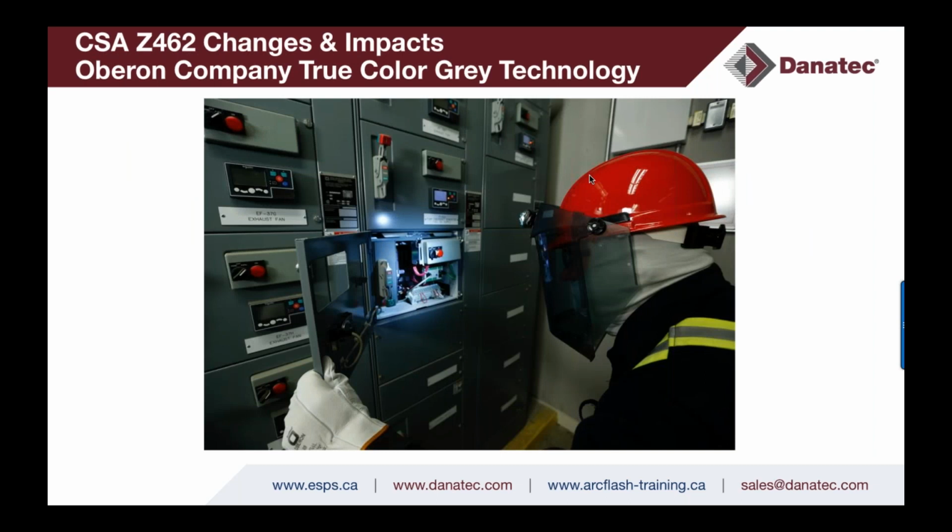So basically that's an MCC starter bucket, a qualified electrical worker, and you can see the light gray tint on the arc-rated face shield. What happens is there is no color discoloration. There's no visual light transmission degradation. And you'll also see a lamp on that shield and the difference that the lamp makes. So when I work with clients, I encourage them to review what arc-rated face shields they purchased. If they have Oberons or Honeywell Salisburys, they should upgrade to this true color gray lens technology and ensure that you have the LED lamp. Look at the difference in the lighting there. It's unbelievable, especially in MCC starter buckets or other enclosed equipment.